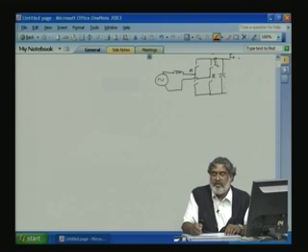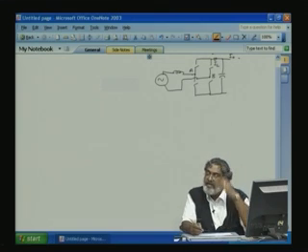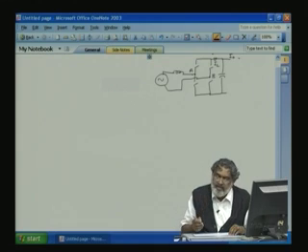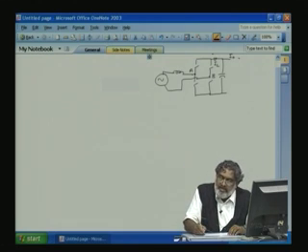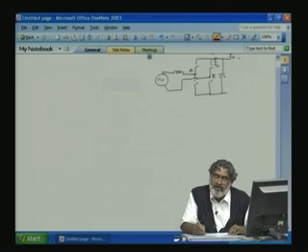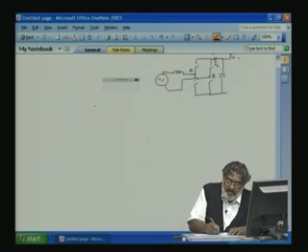That means due to the ripple current, the fluctuating current, the voltage ripple across this should be as small as possible. Small means how much? Okay, 5% of the DC. We can have only that much ripple. So, let us find out what is the ripple current coming here. If you see here, this is VAB, the fundamental component of input power of this converter should be equal to the output power of this one. So, the input power to the converter is equal to VRT into IST, that is coming from here. This is the IST.